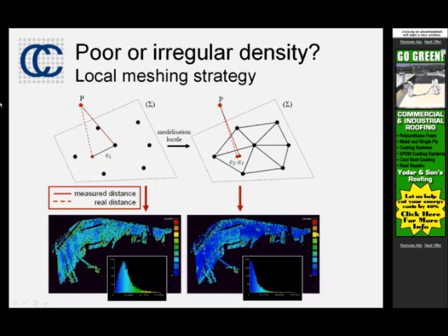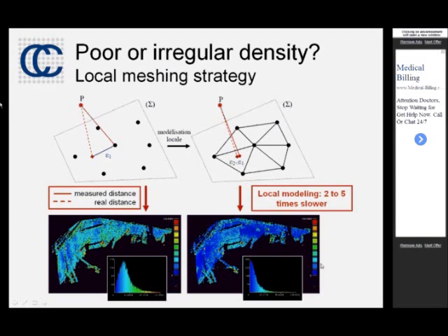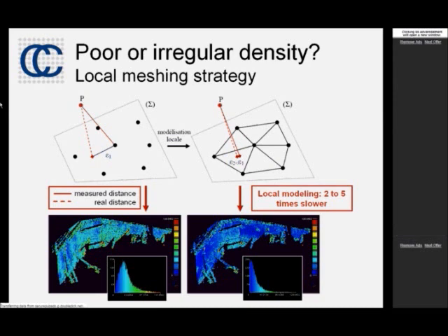It's just a bit slower to compute, and it's important to know that the result is only valid in a global understanding. I'm not sure if it's clear. It's only a statistical result. You get better results on the whole cloud. Locally, you can have worse results, but if you want to consider the global distances distribution, it's generally much better.